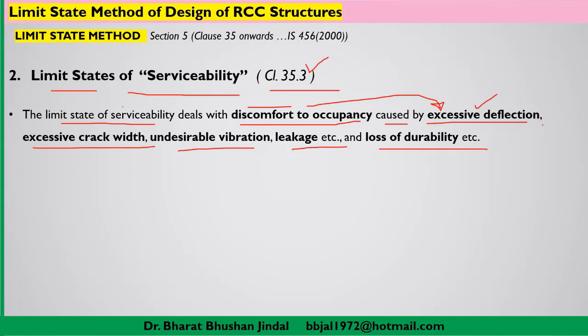So when you are going to design a structure and you are taking care of the limit state of serviceability, first of all you have to be sure that there should not be excessive deflection, there should not be cracks of greater width, or you will be restricting a particular width of the crack, or there should not be any type of vibration, leakage, as well as loss of durability.